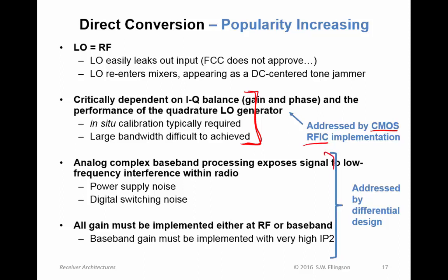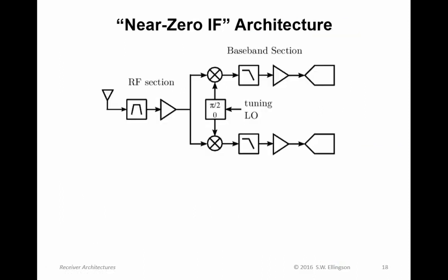Then these two problems are addressed by sound differential design. Because remember, differential design has intrinsically good common mode rejection performance, and good differential design has intrinsically good second order linearity. And these days the community is getting better and better at differential design of these types of circuits.